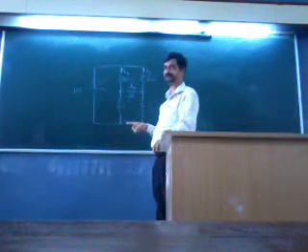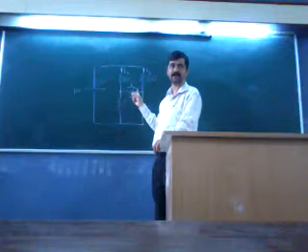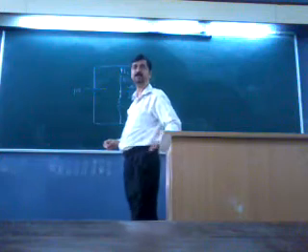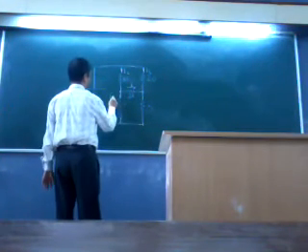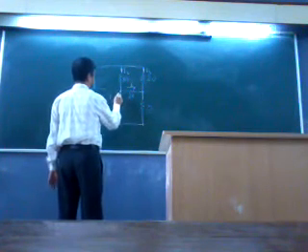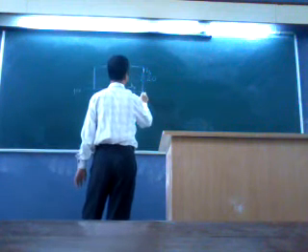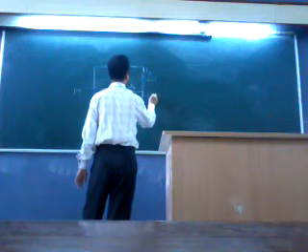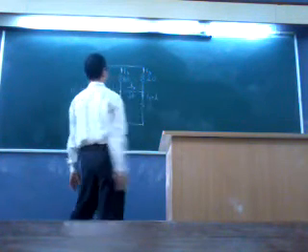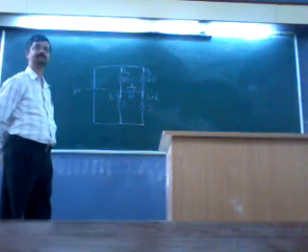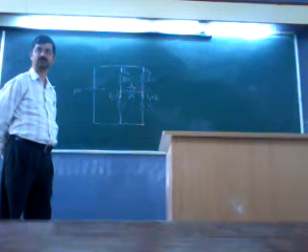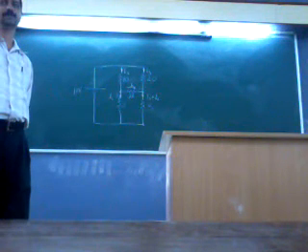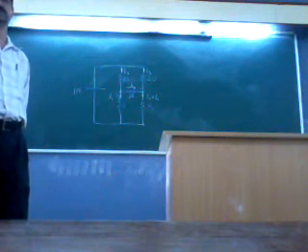So you can very easily find out the other currents. What this would be? This would be I2 minus I1, and this would be I3 plus I1. Is it correct now? It's alright. So Kirchhoff's node law or first law provides us a very simple solution that way.